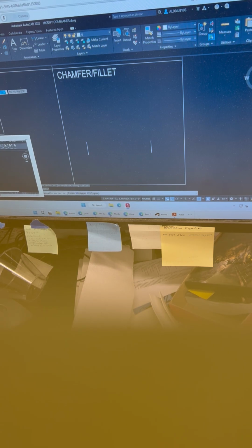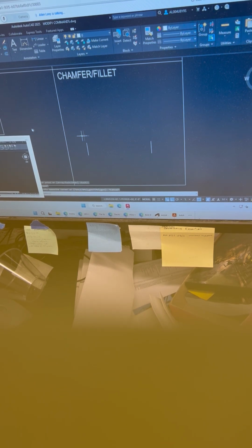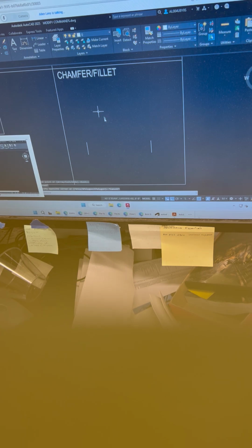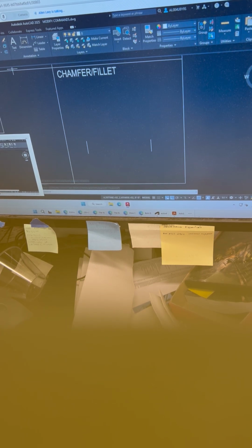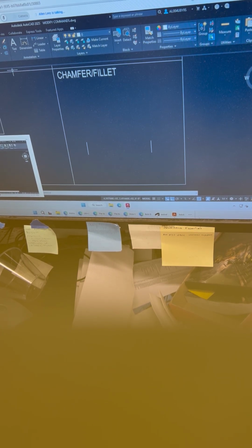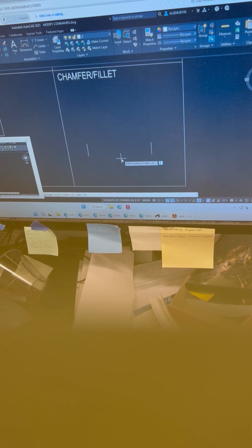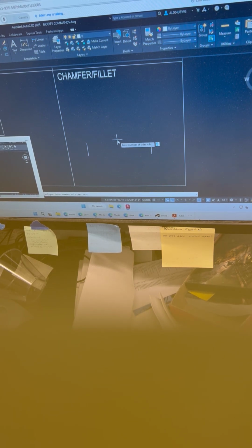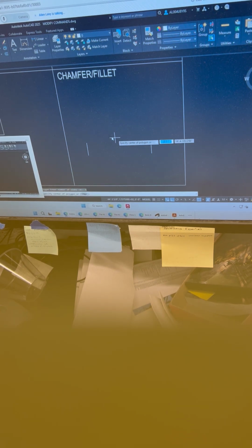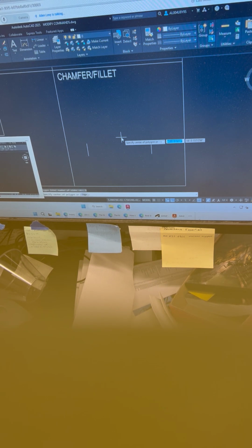All right, now this time, if you move straight up, the pentagon is going to be upside down. That's okay. But if you really want to see the effect of this, try this. Move your mouse straight down. You see how you have your laser beam there. I want you to make sure your laser beam is pointing straight down at 270 degrees, and I want you to type in 1 foot. That's going to be, you're specifying the radius of the circle. 1 foot.